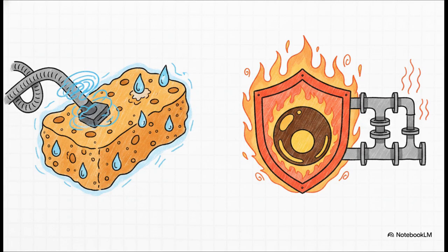So next, we have the modern alternatives, PVE and PAO. PVE, or polyvinyl ether, is fascinating stuff. It's highly hygroscopic, meaning, yes, it absorbs water super easily, but it does not undergo hydrolysis. No way, right? That means it won't form those nasty acids. And unlike PoE, PVE can actually be dehydrated again just by using your vacuum pump. That's why it's incredibly popular in VRF and ductless systems.